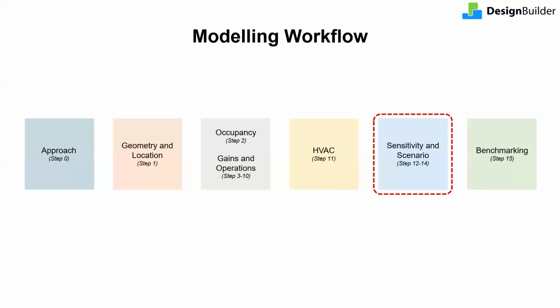Now moving on to the next part, the presentation of results that account for uncertainty. So we have got a deterministic answer now. Let's see how we can better present our model findings. After the initial baseline projection is done, sensitivity analysis and scenario testing should be done at appropriate stages to understand the factors that are likely to have the greatest impact on the energy consumption of the building, presenting the results as a range.